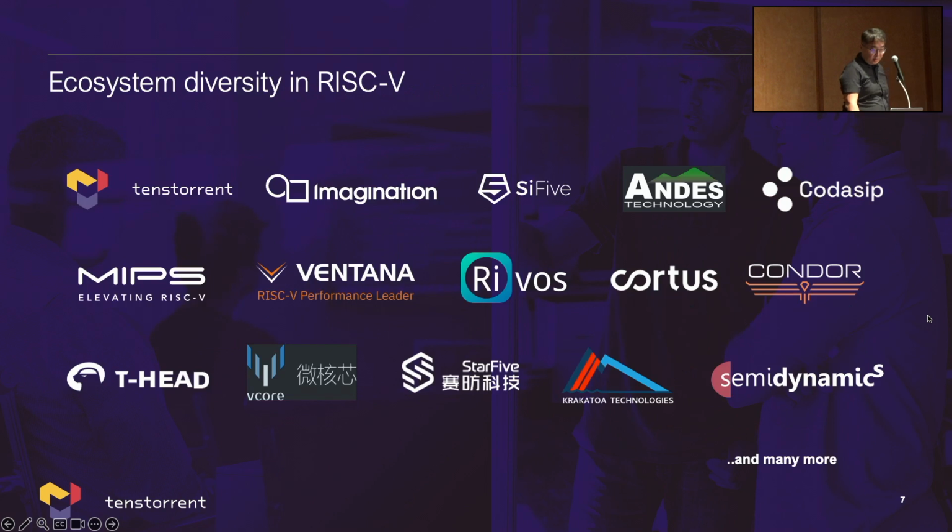You can look at the stability. Currently, all the RISC-V companies in the world are providing solutions for RISC-V IP. Some of them may be system design companies, some provide the IP only. But the diversity of potential IP sources is much, much better than ARM. This is a critically important thing you have to remember: when you're choosing an architecture for your project, make sure the IP supply chain is there, so that you will not be controlled by one single company for your future direction.